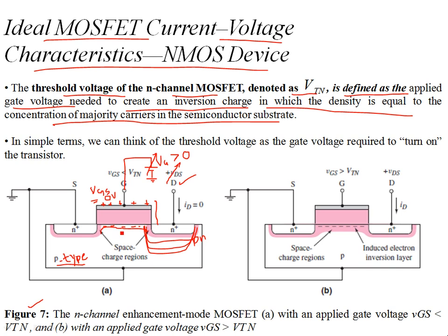The holes are going to accumulate somewhere at the bottom of the substrate. Due to the electric field, due to the energy present over here, these atoms are going to lose electrons, and these electrons are going to be attracted to the metal and semiconductor interface. The electric field direction is as such, established inside the dielectric. It's a capacitor.